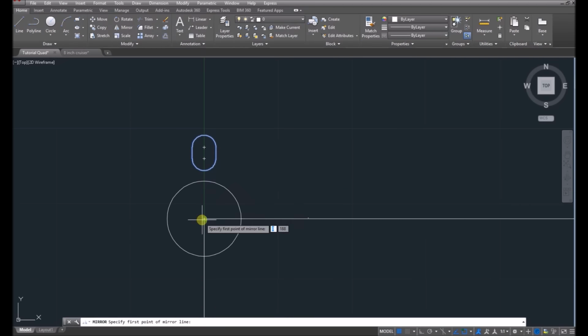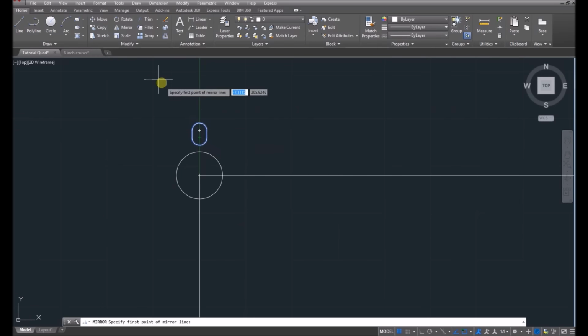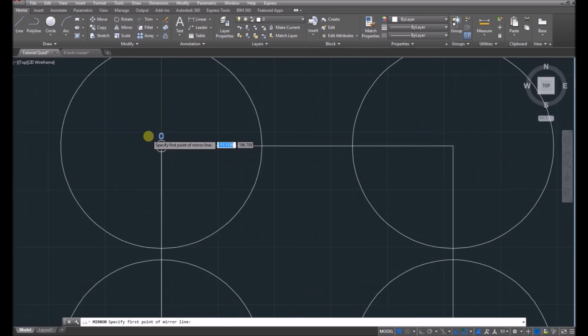So what I'm going to do now, see, this tool's really handy, the mirror tool. If you've got a pure X frame, you only have to design a quarter of a frame, then you can mirror it over twice. And I'll show you what I mean. So I've got this here which I've designed. I obviously need one on the other side exactly the same. So I select my piece, I click the mirror tool. Now, I have to click the middle of the circle because that's the part I want to mirror it from, if you know what I mean.